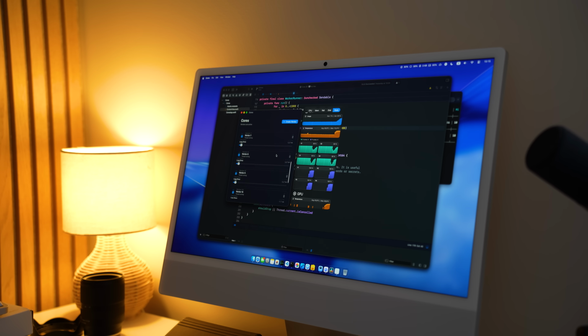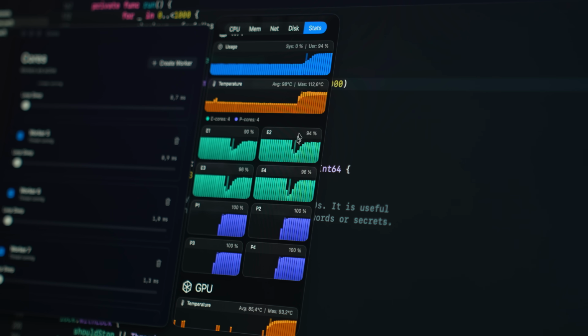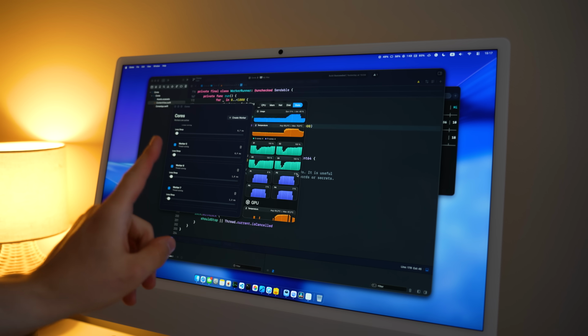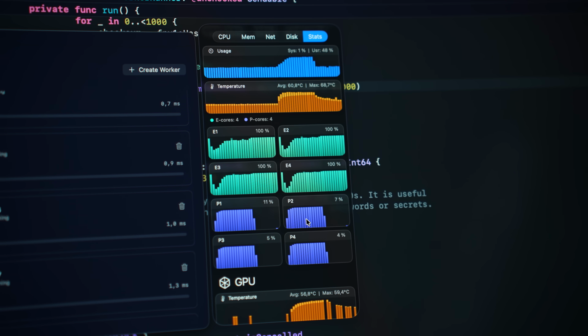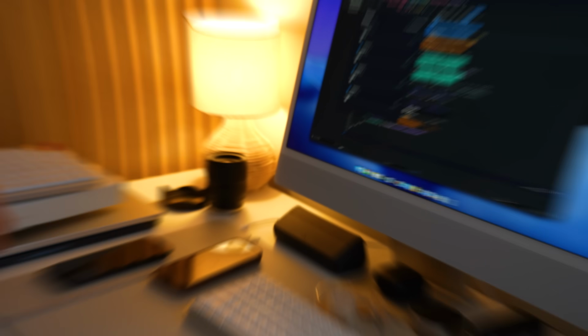Alright, so the reason we're doing this is because I really want to discover for how long the CPU can sustain an absolute maximum load. Because finally, as you can see, we are activating all of the cores, and it's only a matter of time before it starts throttling. And it honestly didn't take very long at all. So each of these bars is 5 seconds. So it was 1, 2, 3, 4, 5, 6, 7, 8, let's say 20 times 5. So the CPU is willing to use all the cores, but only for a short while, maybe a little over a minute and a half.